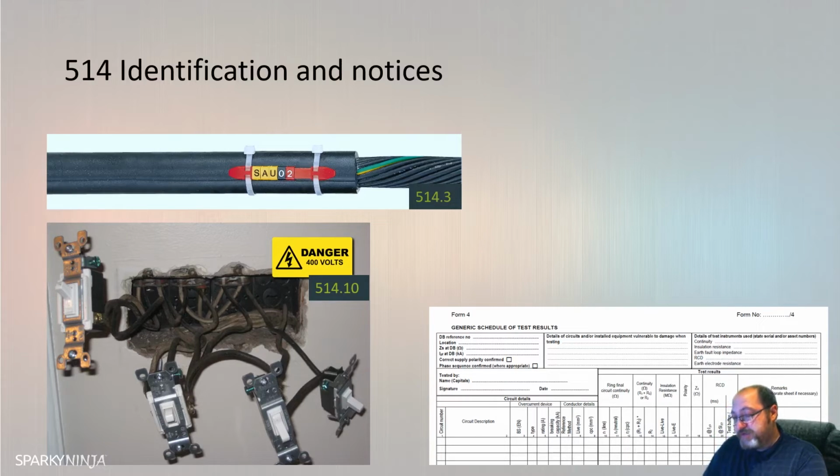514.3, identification of conductors. Except where 514.6 comes into account, cores of cables will be identified by colour or letters and numbers. Every core of a cable shall be identified at its terminations and preferably throughout its length. With colour, neutral or midpoint: if a circuit includes a neutral or midpoint conductor identified by colour, the colour will be blue.